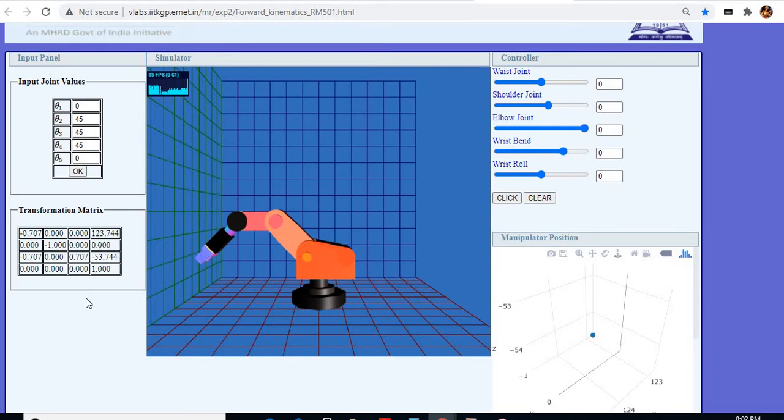Generally, the RM501 drive unit provides the intelligence and control for the robot unit. The drive unit computes all the arm control information for each instruction. It handles arm velocity, acceleration, deceleration, and movement trajectories for the user. The drive unit is interfaced to the computer host processor through a controller interface.